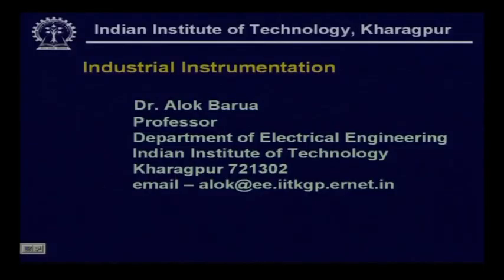As you know, there are some sensors like LVDT and thermocouple that need conditioning circuits. In the case of LVDT, we need circuits for null voltage reduction and for phase compensation, because in an LVDT there is always an input-output phase difference. That can be corrected only by using signal conditioning circuits. For the phase compensation, we need some lead-lag network type of things, so that the input and output are in the same phase, because we need excitation in the case of LVDT.